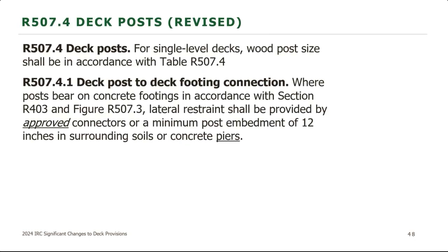And again, that's going to stabilize the base of that post. Either an approved connector, and again, approved whenever you see that in the code is approved by the building official, or else into soil or a concrete pier. You need that 12 inches of embedment.